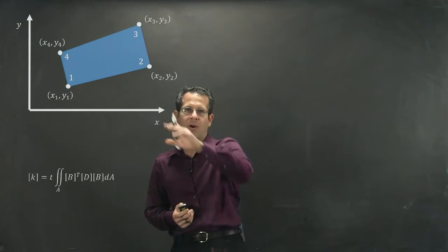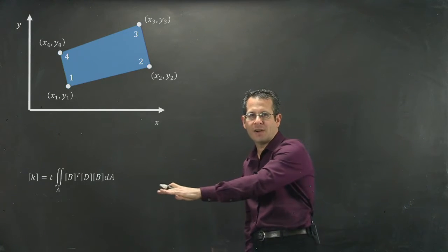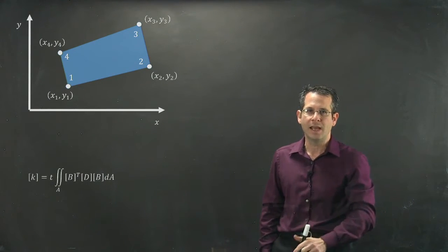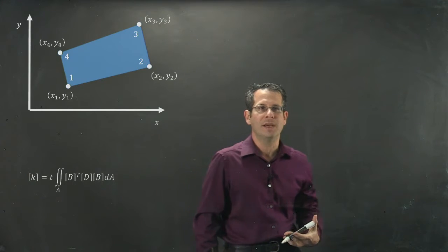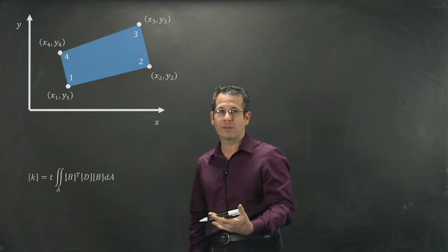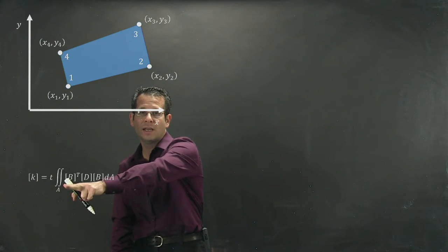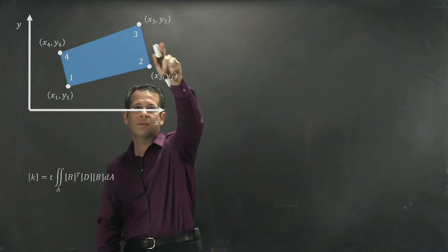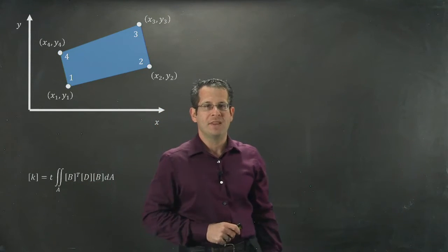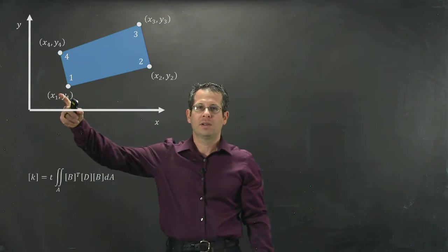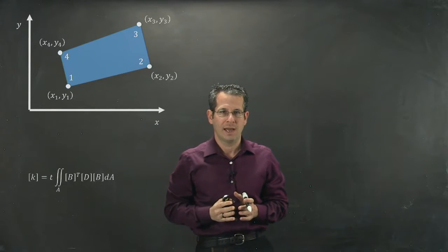I'm leaving up here an example of a generic quadrilateral element, and I've replaced my total formulation for the rectangular element, and I've just placed up here our formula for the K stiffness matrix. I've simplified it a little bit. We're in two-dimensional space. We're modeling our three-dimensional element as a two-dimensional element. So that triple volume integral I can think of as an area integral, integrating over the area of our quadrilateral element and then multiplying it by a constant thickness.